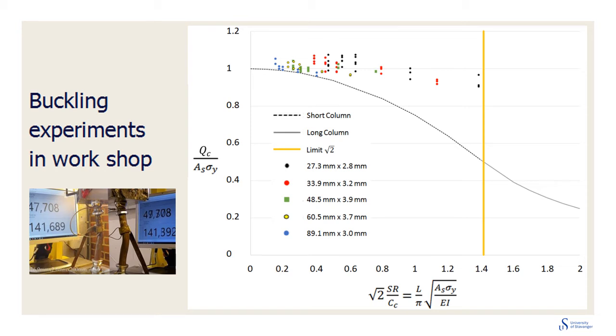Buckling experiments were conducted in the university workshop for several pipe sizes with 3.5 inch as the greatest outside diameter. All selected buckling lengths correspond to the Johnson parabolic formula discussed previously. Both ends of the pipe were free to rotate using a ball and seat arrangement as seen in the picture. Axial force and displacement were logged and also displayed on a computer screen. Two cameras were rigged up 90 degrees apart to film these experiments, showing both the shape of the pipe and recorded data. The Johnson formula was found to give a safe estimate of the critical buckling load.